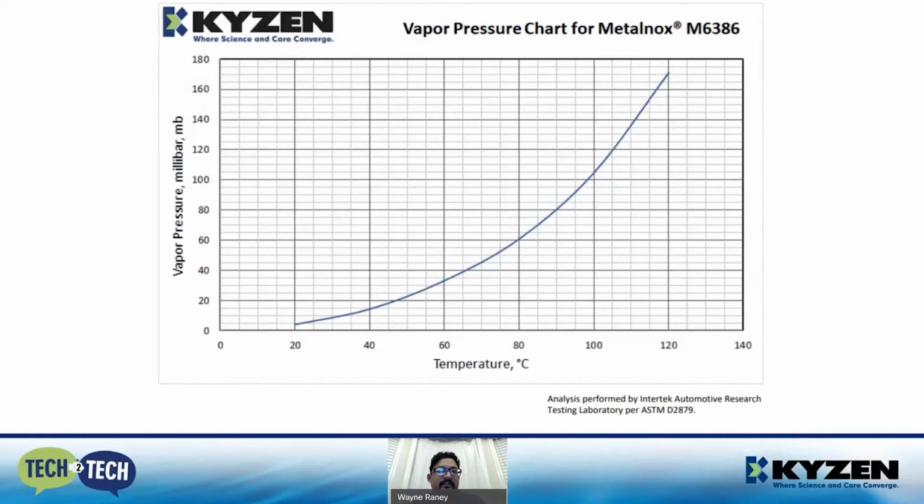That's approximately 161 Celsius. As the temperature of the part goes up, then it has a tendency to flash off the fluids. This is important to note, especially in the drying phase where the deepest vacuum is drawn. As the pressure drops even farther with an extremely hot temperature, superior drying is accomplished. The fast pressure drop is like quickly going to Mount Everest where the pressure is low and thus the boiling point is even lower.